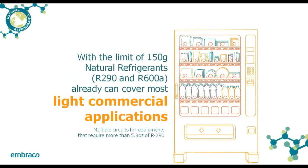With this 150 gram limit for R290 and R600a, most light commercial applications can be covered using these refrigerants. When you need a charge larger than 5.3 ounces, you may have to look into using dual circuits to achieve this charge limitation. And this is what we're going to focus on, adjustments to the system to help hit these limits.